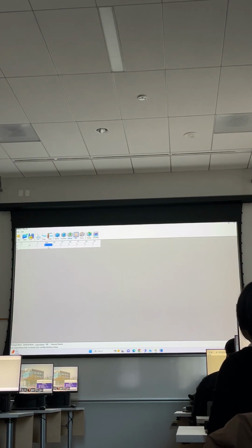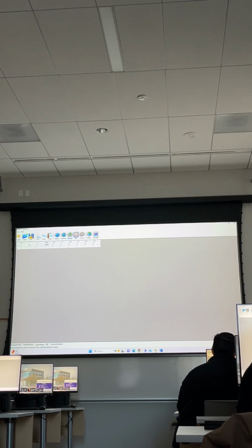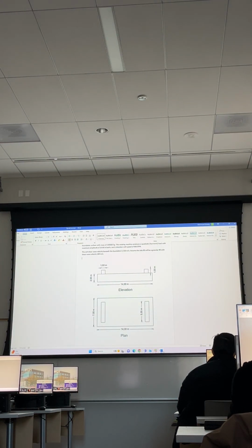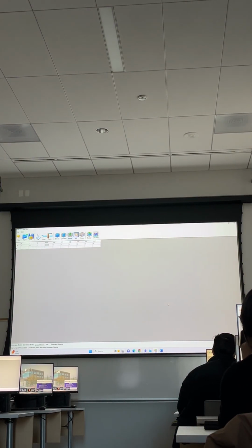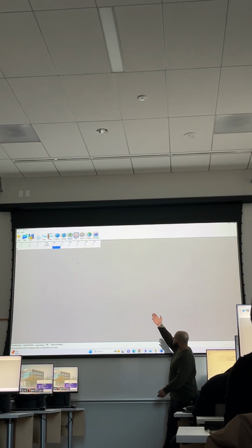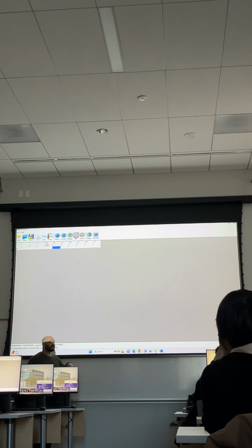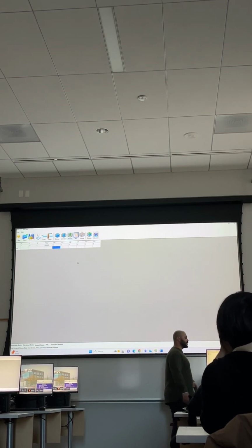And the mass, again, we need to define the mass in kilogram. It gives you everything in kilogram. I just put it here. Okay. If in your example or in your project or assignment, whatever, he gives you the IX, IY for the equipment, that's okay. Just define it here. In our case, we don't have this information, so we just neglect it and just define the mass.